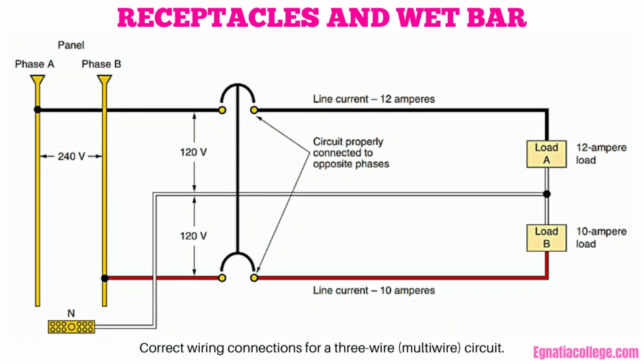Take care when connecting a 3-wire circuit to the panel. The black and red conductors must be connected to the opposite phases in the panel to prevent heavy overloading of the neutral, white, conductor. A 2-pole breaker may be used for this purpose, but is not mandatory for multi-wire circuits serving fixed lighting and not split receptacles, Rule 14-010b. The neutral conductor of the 3-wire cable carries the unbalanced current.